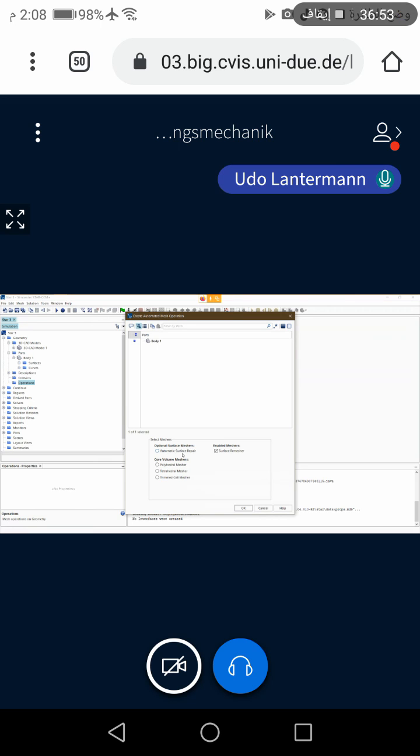If you want, you can choose automatic surface repair. I will choose it now. You can do it as you want. Then you can choose the type of the mesh you will create. You can choose polyhedral mesh, or trimmed, which means hexahedral, or tetrahedral meshes. But we want to create hexa meshes, so we choose the trimmed cell mesher, the third option.